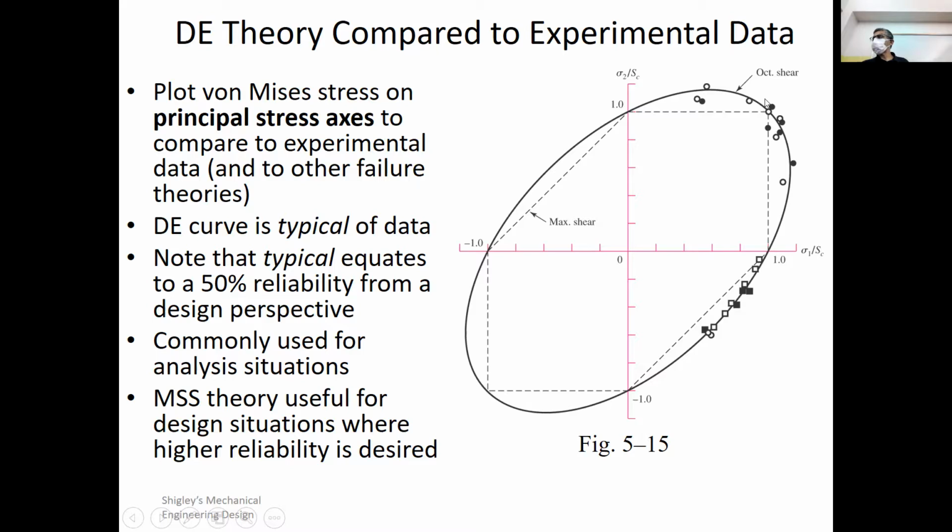So in this case, that would be the yield strength. And you notice that the yield strength in tension is the same as the yield strength in compression. So that's why I end up with a square here and a square here that are equal.